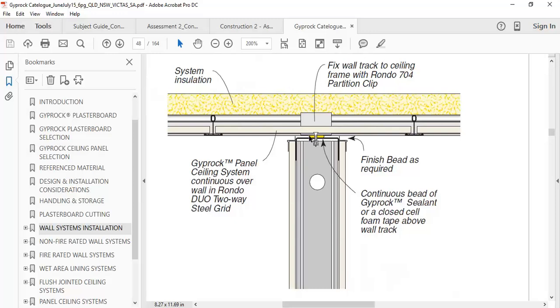I haven't drawn any of those things, but just looking at the wall: the plasterboard, that's right, so that should be noted. The stud, that should be noted. And the top plate, that should be noted. Even the ceiling has got a note here. But then you've got the fixing, attached by or fixed by.